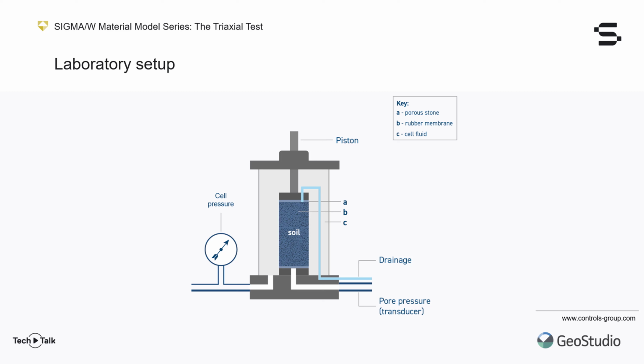Once the sample has undergone a consolidation stage, which we will be discussing in a moment, the sample will be loaded. A triaxial test is traditionally strain controlled, meaning that we will impose a deformation upon the sample and measure the force reaction. Stress-controlled tests are also sometimes carried out, but they are unstable by nature when the sample's behavior is brittle. To load the sample, a piston pushes the top cap of the sample downward at a constant rate of